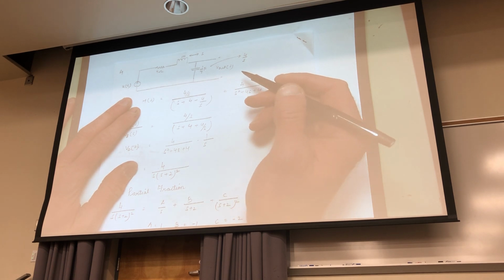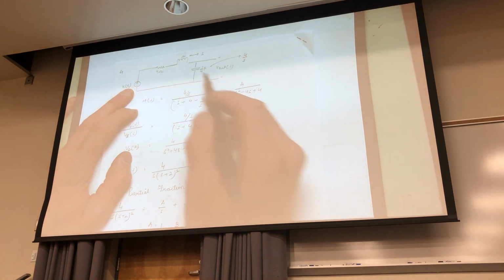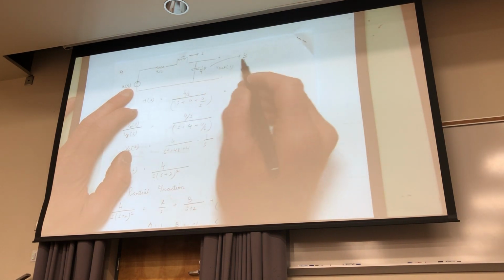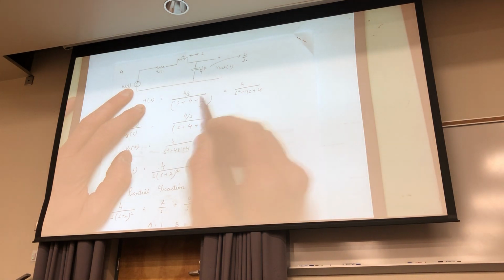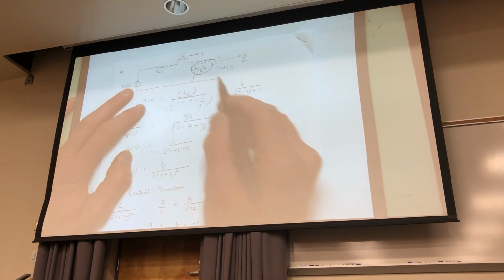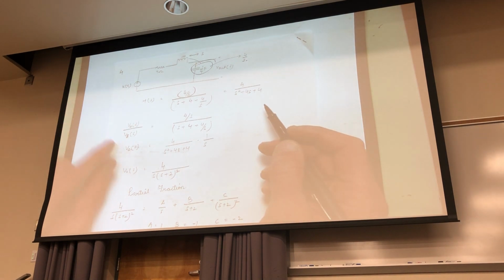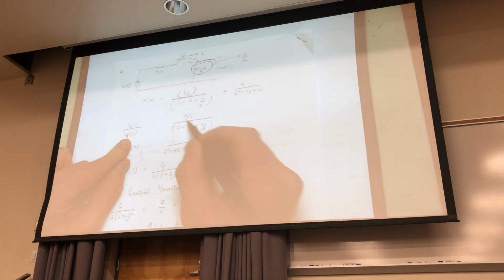So if you looked at this, it was a template. The only difference is the values of R, L, and C. In a sense, only really a couple values. So here I have U of t. I have 1/4. This is 1. So this is 4. This is S. This is 4 over S here. And this is simply 1 over S. My transfer function is the output impedance right here over the sum of these impedances, S plus 4 over S. And then I multiply it by the input, which is, excuse me, 1 over S.